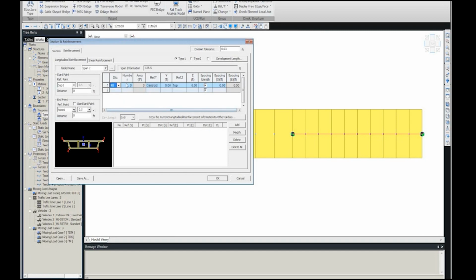Diameter we are using the same size. Number will be 30 this time because this will be right here beside this. 0.2 and 0.5. Span 1, that's correct. Apply. And the next one will be the middle span to support 2, and we are just changing the number to 20 of them, okay? And add. So simply later on, if you want to change these, you can come back here and make the changes. On this diagram, you can see the arrangement of these bars.